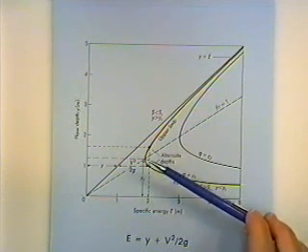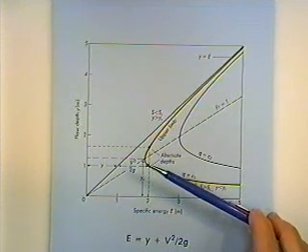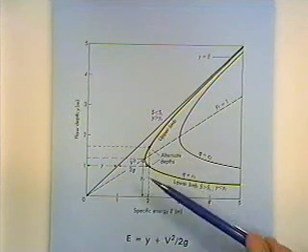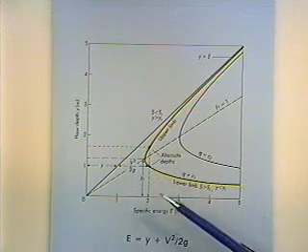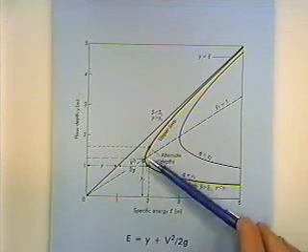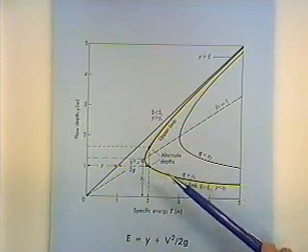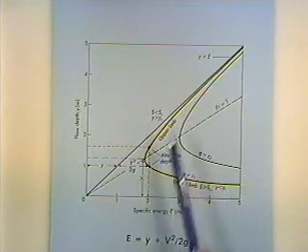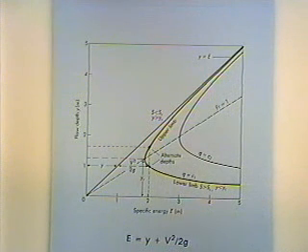By definition, critical flow is a condition at which specific energy is a minimum. And so for these different depths, specific energy is a minimum right here at the critical depth. And as we change slope or change something, the depth and velocity head will trade off, and we'll get a curve that looks like this.